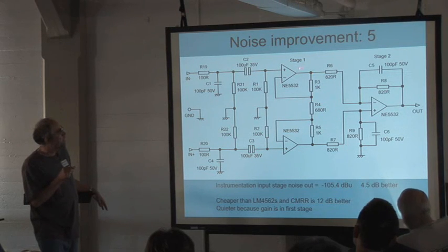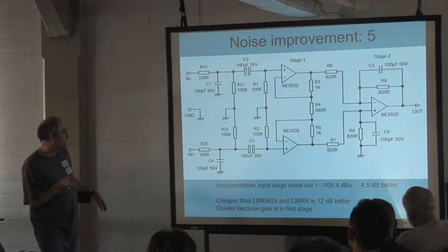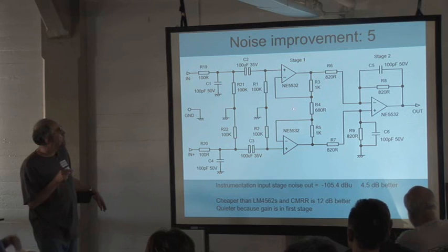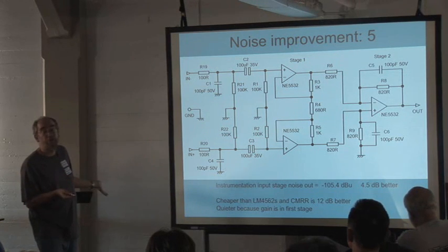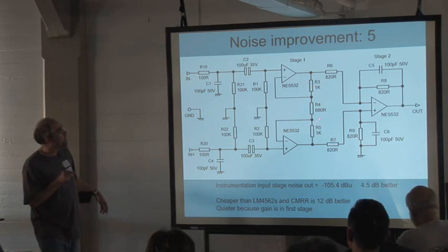So if you've got significant gain in this stage, then you gain a common mode rejection improvement of the gain of that stage. This here, I think I've set that for 12 dBs. Yes, I have. And so I get 12 dB common mode rejection improvement, always. It is bulletproof. It is absolutely solid. It does not depend on the op-amps. It does not depend on the resistors. These two don't have to be that well matched. That's an important thing. Now, they will affect the overall differential gain if they're out, but the common mode gain will always be 1.